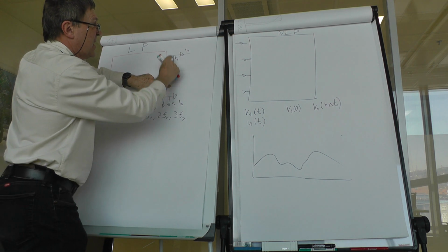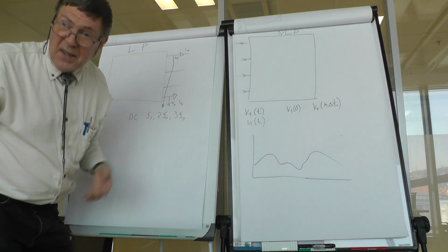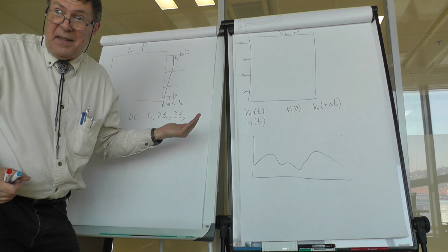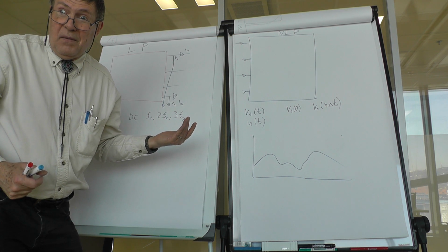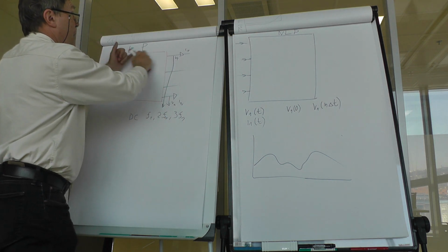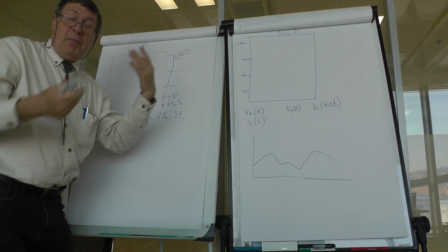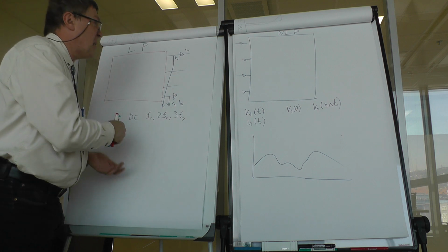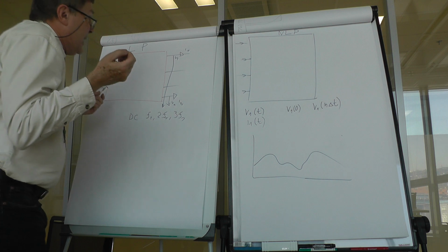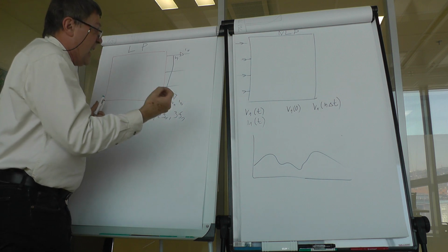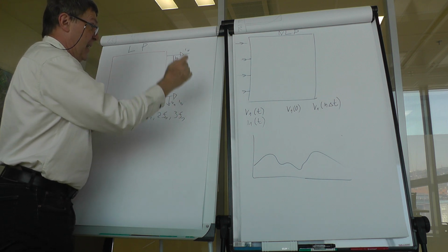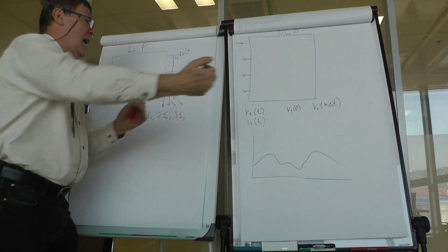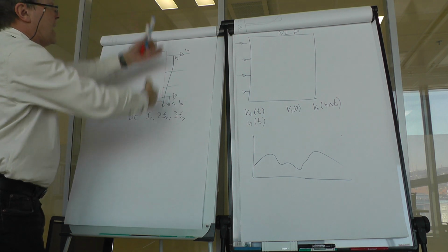I know the currents on all of the terminals or ports, and I can run an analysis of this N-port and get out some kind of parameters, be it Y parameters, be it S scattering parameters. Anyway, this analysis would give me at each frequency components of the voltages. So I have currents at the input, I get voltages.